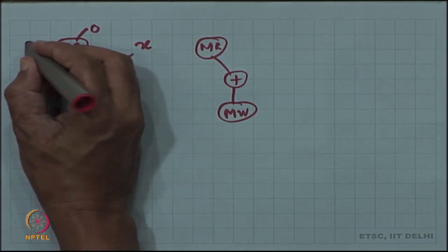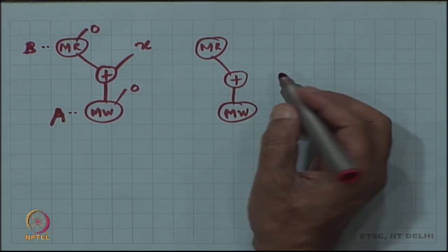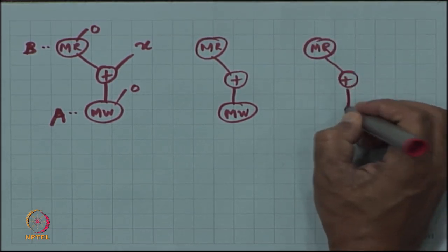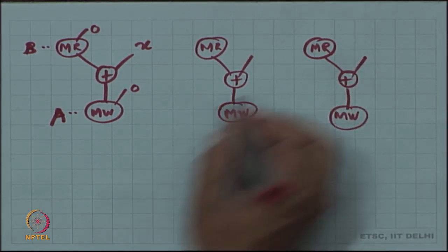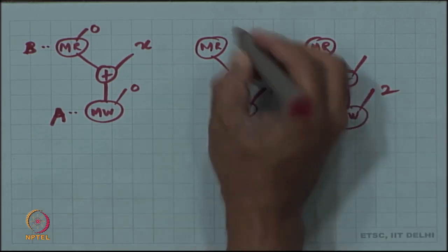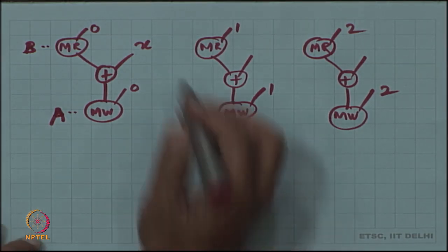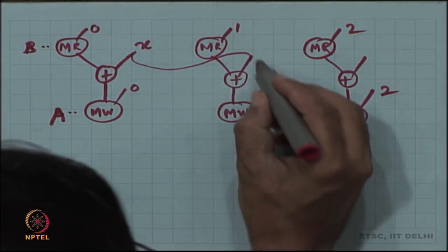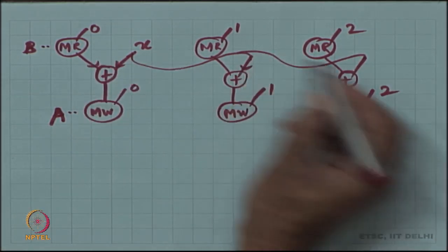Yes. Okay. So I have 3 copies. These are changing, the addresses are changing, but they are changing in a way that they are statically known. What else should I do to this data flow graph? This x is actually common to all the three. So, I can actually move it here, something like that. That's also using the memory 3 port.